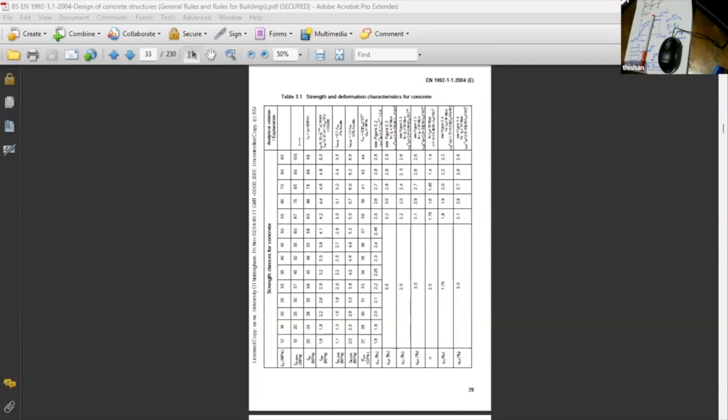What can we do? We can calibrate the PDA results for that particular site rather than using data from other sites. Right? Then we know for the specific rock available at that particular site, having its own peculiarities, we have calibrated the PDA by comparing the results of maintained load test and PDA. So once the calibration is done, your predictions from PDA will be for that particular site, and we can be sure what we are doing.